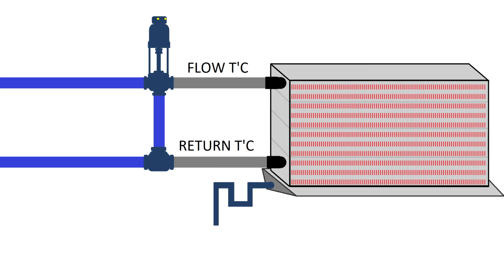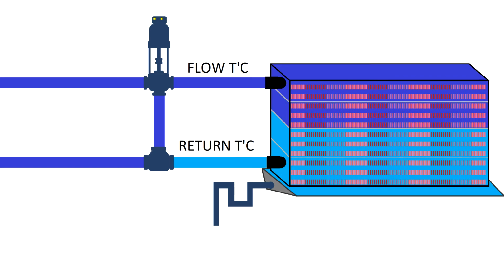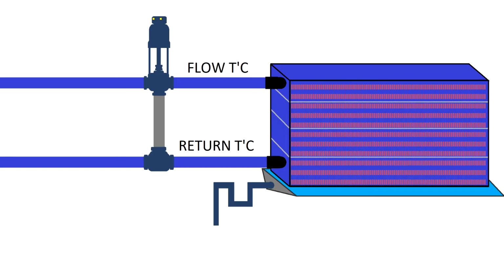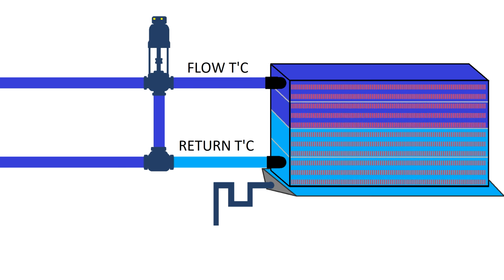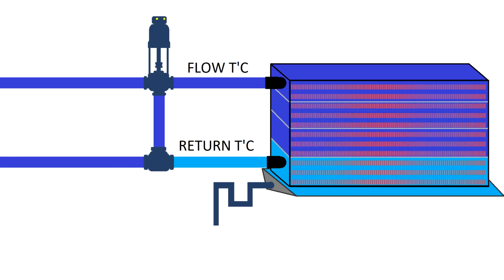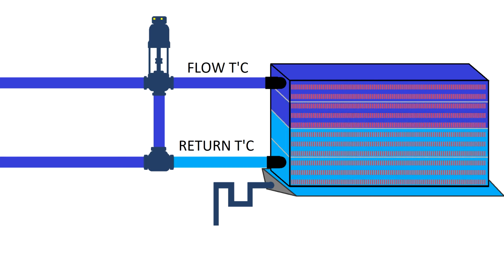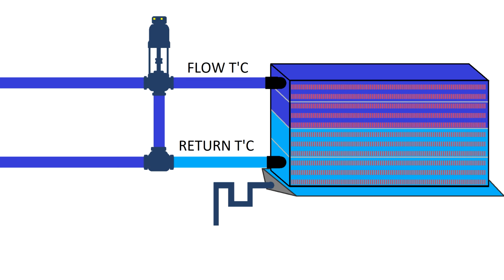Just like in a heating situation, when we talk about cooling, the cooling agent flow must be constant and the temperature must be constant. So the PID, proportional integral derivative, will try to control the temperature, so the temperature won't have a very big variation.